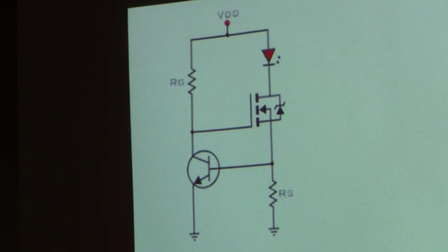If you've got a really high load on there and the current is ramping, every time the voltage across the sense resistor goes up a little more, the NPN pulls a little harder until it pulls too hard and cuts it off and the current drops. Then it cuts off less, gives up a little bit, and the gate comes back up. So it quickly pulls the gate down and asymptotically approaches the nice smooth level for constant current.